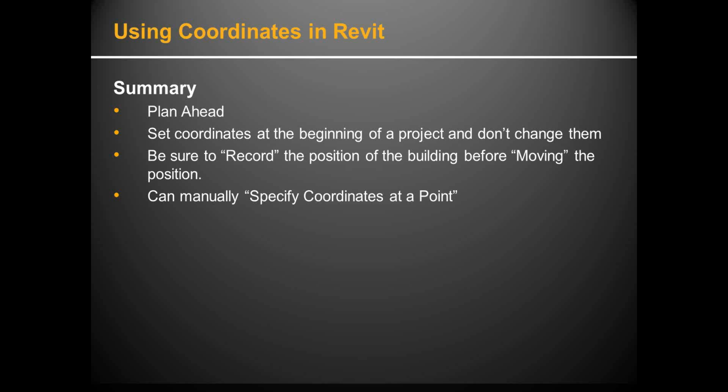It says, we have an MEP firm. I'm just following up reading James' question here. We have an MEP firm and had an architect realign his model to match the civil, and it threw all of our MEP families off. We don't host because we have had architects delete objects, which deletes our families. I believe if you delete objects in the current version, they just become orphaned or unhosted. They stay in the same place, fortunately, which is much better than older versions of Revit.